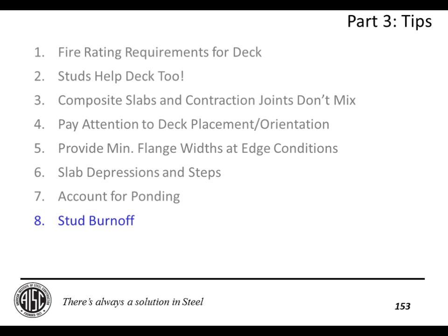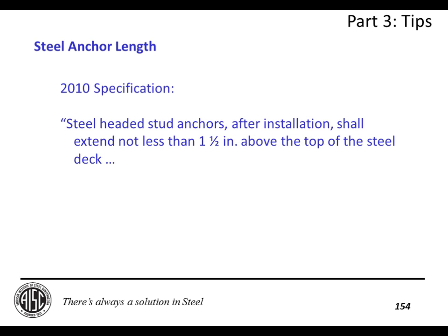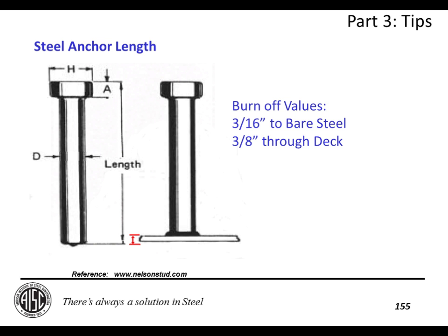Number 8, stud burn-off. Be aware that this is an issue. The 2010 spec requires that studs do not extend more than 1.5 inches above the top of the steel deck. And when you specify the length of the stud, when they weld it down, it is going to get shorter. When you weld it through bare steel, it shortens by about 3/16 of an inch. And when you weld it down through deck, it shortens all the way up to 3/8 of an inch. So I would recommend that you specify the installed length of studs on your drawings so that they order their studs to take into account this burn-off value, and you don't end up with studs that are shorter than the minimum requirement.